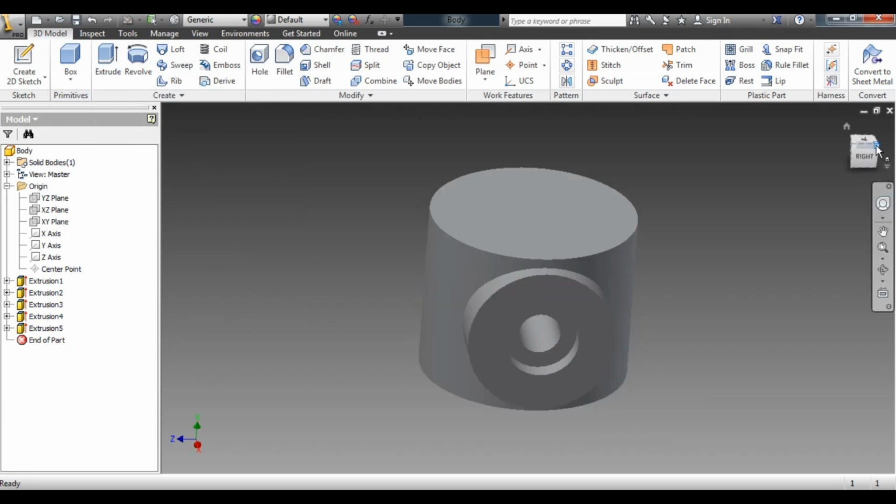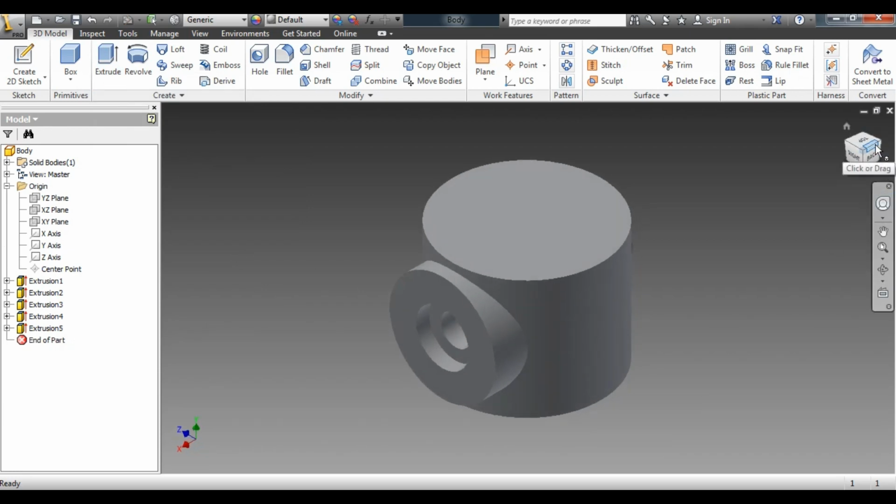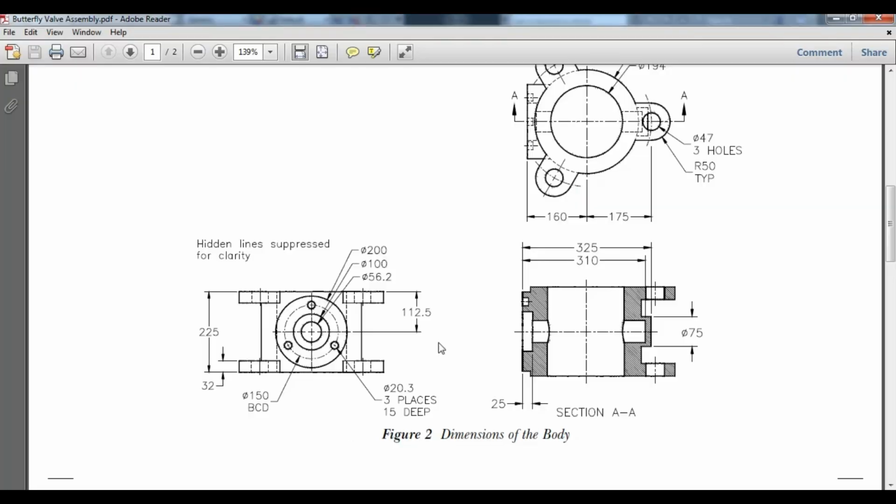Okay, now the half portion is over. Only then can we go directly to the main hole. This is the hole I am going to create. The reason I did not create it first is that if you create it and then do all these operations, the extrude will occur inside. For that reason, first I will make the hole command and the extrude command.